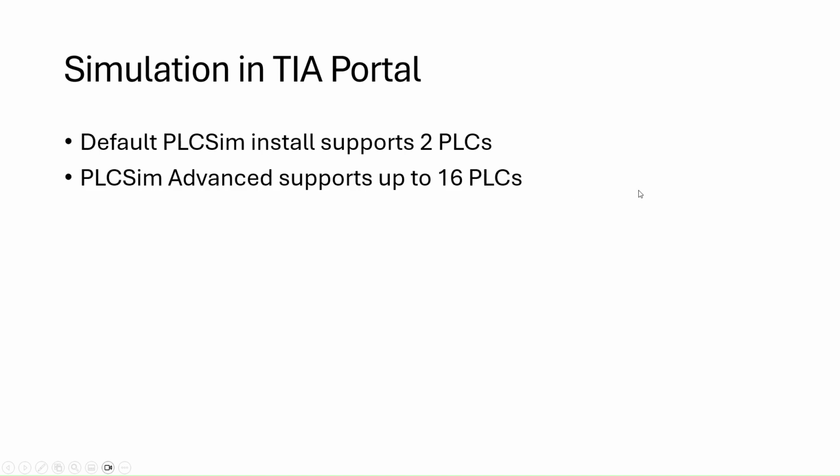So if you have more complex projects, larger projects with more PLCs, you can use PLC Sim Advanced. With that, you can have support for up to 16 PLCs. That depends on the number of cores you have on your system. Each simulated PLC will take up one core, so you already need 16 cores to simulate 16 PLCs. But if you agree with me, that would already be quite a complex system with 16 PLCs running at the same time. But it is possible.